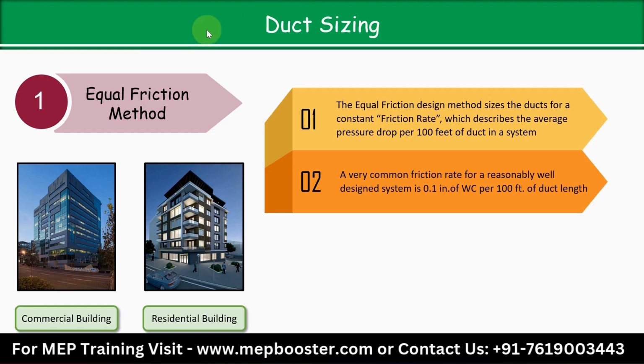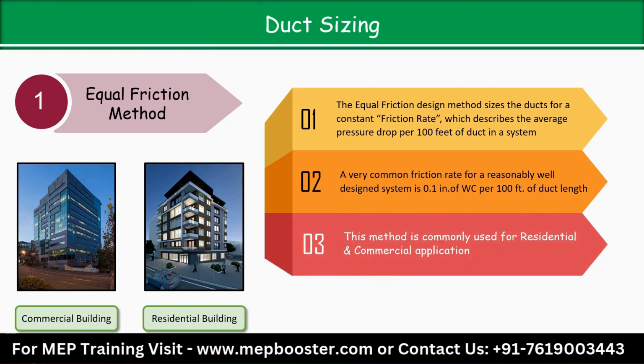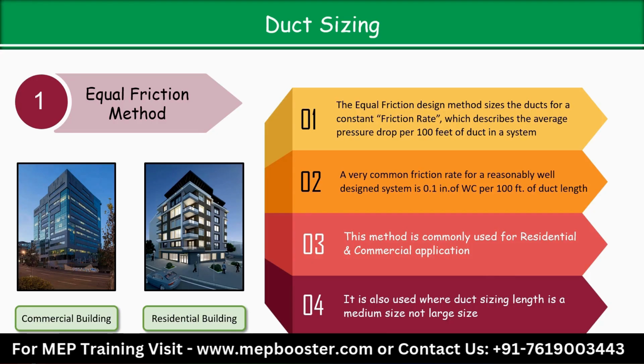And the next thing here, this method is commonly used for residential and commercial application. If you are running the duct work in a residential and commercial building, you can use this method. It is simple and widely used, especially for low pressure duct systems, and it is also used where the duct length is a medium size, not larger size. Is it clear?